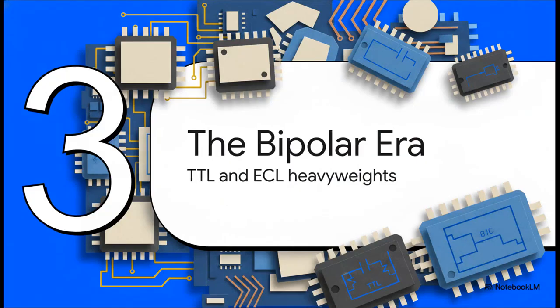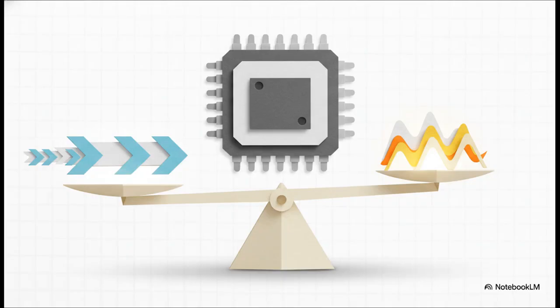Moving on to Section 3, the bipolar era. This is where we meet the heavyweights like TTL and ECL. Enter transistor-transistor logic. You will see this universally referenced on exams and datasheets as the standard 7400 series. Seriously, if you see a chip starting with 74, you are looking at TTL. This family became the absolute standard workhorse of the entire industry because it finally struck a manageable balance. It was noticeably faster than RTL or DTL, and it settled right into a nice medium zone for power dissipation. Was it perfect? No, but it was incredibly reliable.